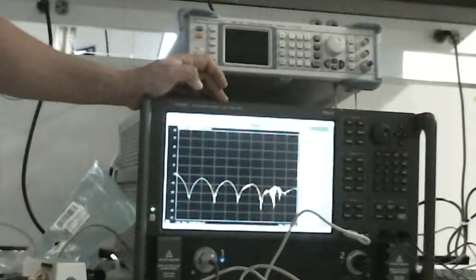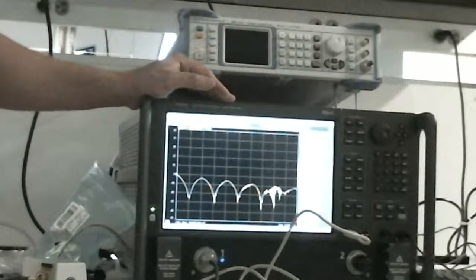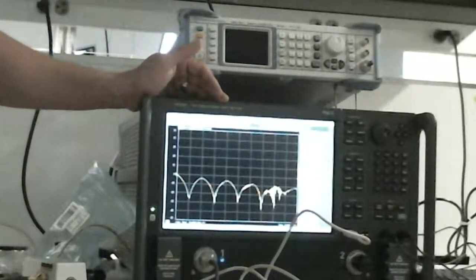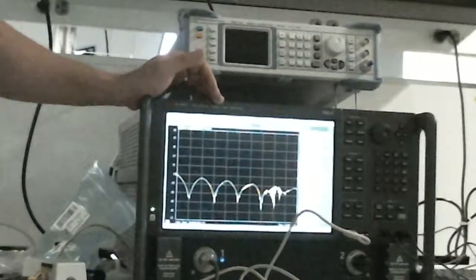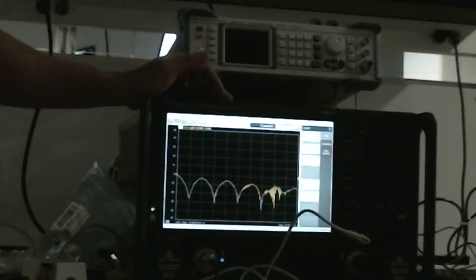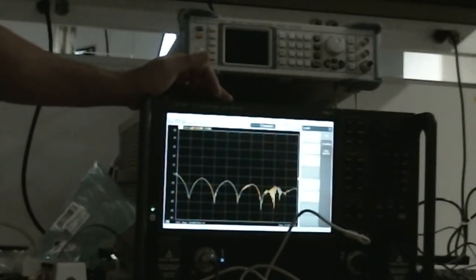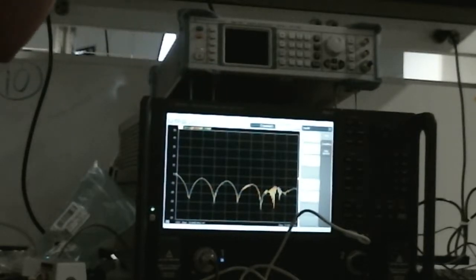So for antenna measurements, typically you're looking at return loss, right? The main limiting factor for return loss in terms of error terms is actually a term called directivity, and that's basically, if you think about a directional coupler, right? It's effectively the amount of signal leakage, so the isolation, in the coupler, relative to the amount of reflected signal that you're going to measure, right?